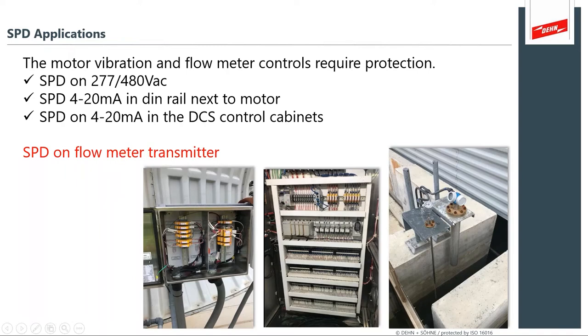Is there an SPD on these flow meter transmitters that are out at the remote parts of the site? And this is what's important. You need to look at those exposed victims and apply surge protection at the point of use.